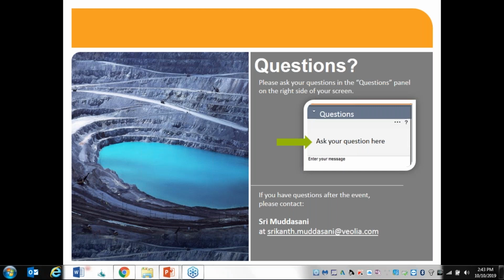That's a very good question, Jill. When you have a TDS limit and a sulfate limit, you are not going to reduce TDS, because what's happening in the advanced two-stage sulfate precipitation process is we are adding a source of aluminum, mainly aluminum trichloride hexahydrate. So we are replacing some of the sulfates with chlorides. That means your TDS will not get reduced.